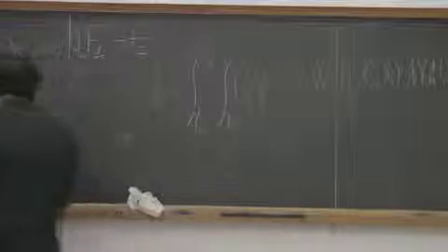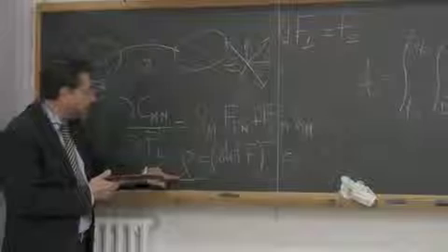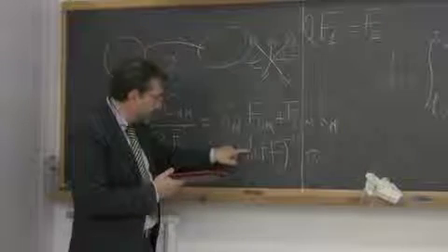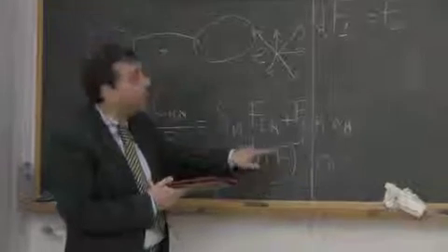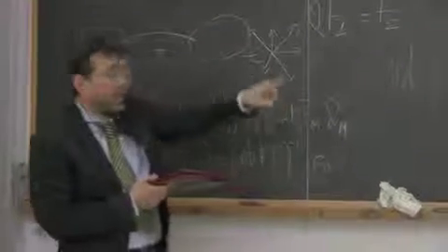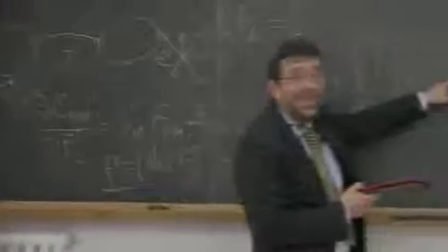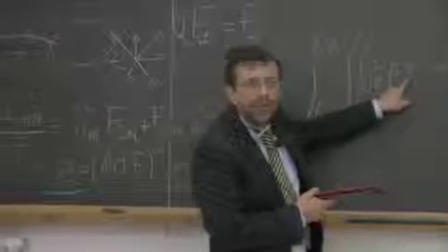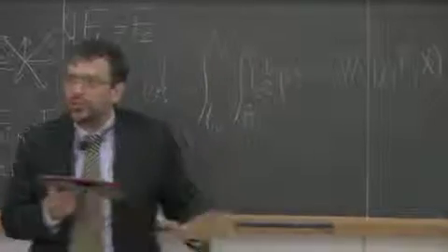If in fluid dynamics you forget that rho is related to the determinant of F, which is the gradient of chi, and that V is the derivative with respect to time of the same function, you are lost.